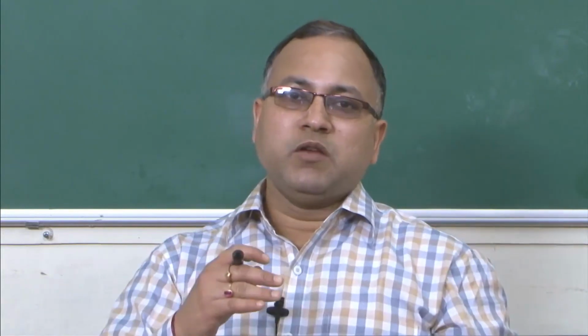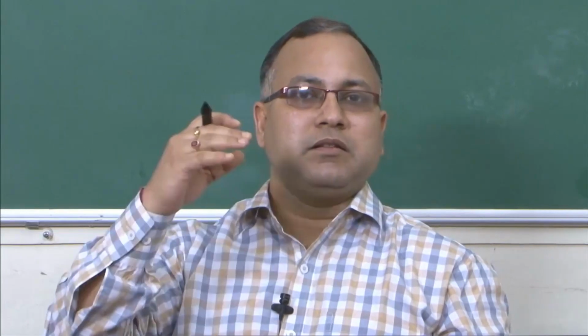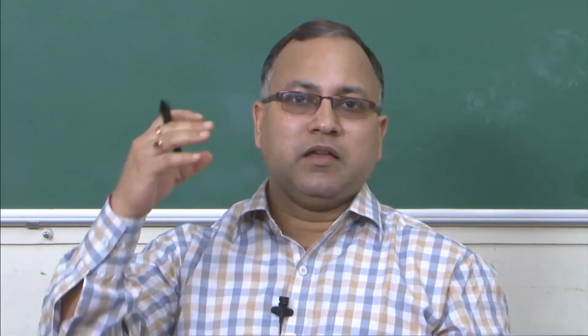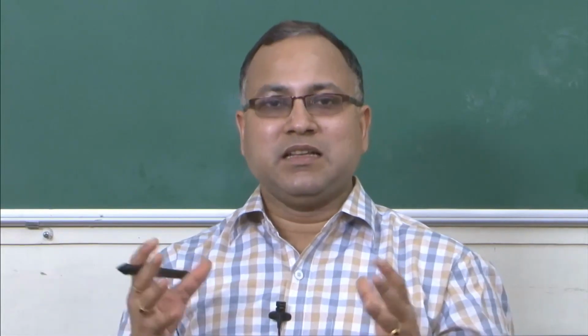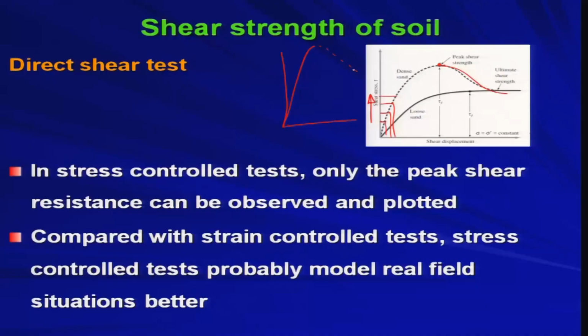So you are increasing the load, and that increment of load eventually causes an increment of stress. Similarly, you can consider a dam or embankment construction. You do not build the dam overnight. You go for the first lift, then the second lift, then the third lift, and so on.